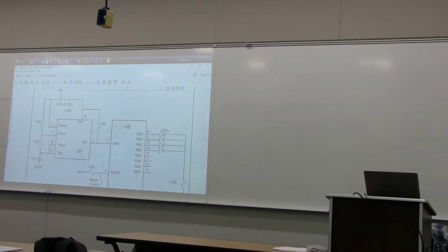So put an alligator clip in here, run it over to a jumper, connect that to the red line. Red is traditionally used for power, and blue or black is traditionally used for ground or negative. So plug that into the red line up there, and take the negative and plug that into the negative line. I put them on opposite ends of the board just to minimize the chance of them shorting. Otherwise, if I put it up here, they're kind of close to each other and so on. And then over here, run a pair of jumpers.